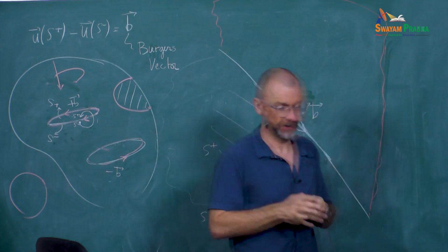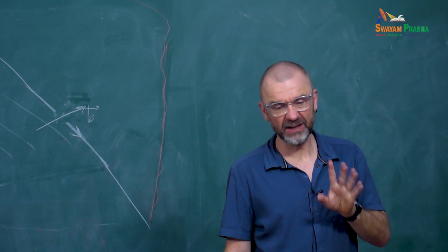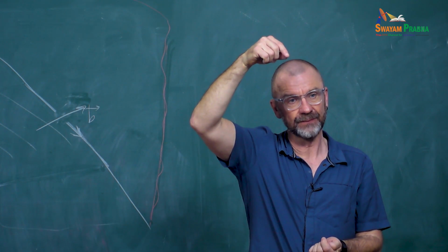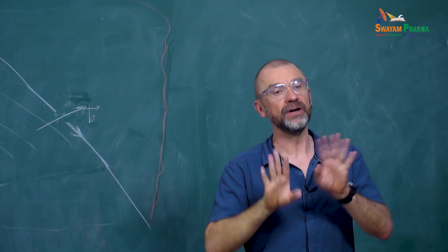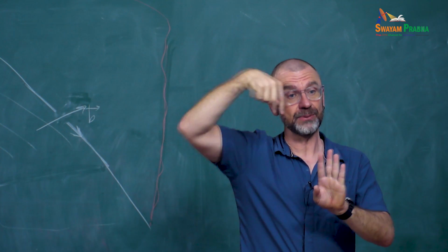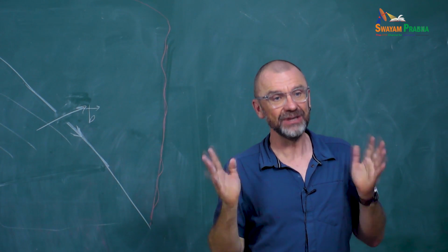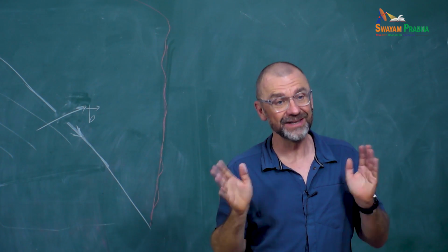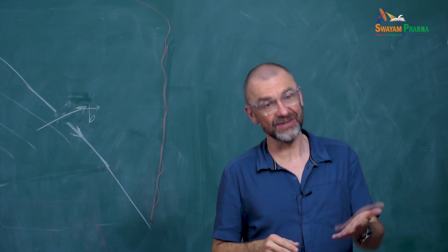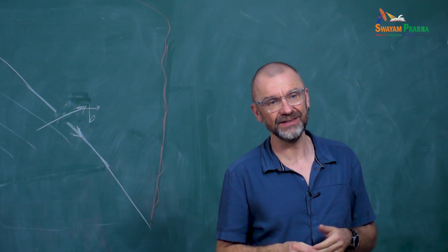It's clear, yeah? You always have dislocations in metals or in crystals in general, just because very often a crystal will grow around a screw dislocation. We're going to go back to the drawings of a screw dislocation, but with a screw dislocation, you have a step on the surface. And so atoms will go on the step, and we let the crystal grow, but in the middle, there's a screw dislocation. So initially, even if you have never deformed your crystal, you will always have a minimum number of dislocations. And then these dislocations can serve as sources of other dislocations, and that's it. So that's one easy source of dislocations.